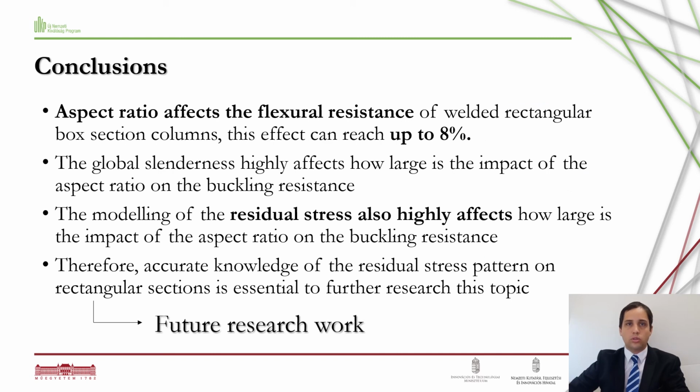As a conclusion, I would like to summarize our results. It is found that the rectangularity, so the increasing of the aspect ratio, could reduce the normalized column buckling resistance by up to 8%, which is currently not considered by standards.